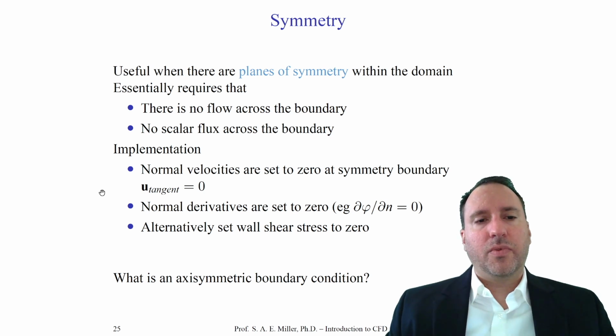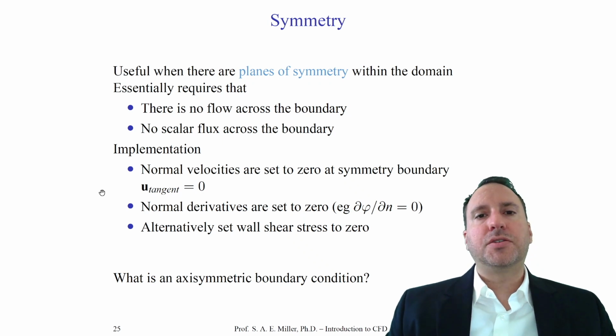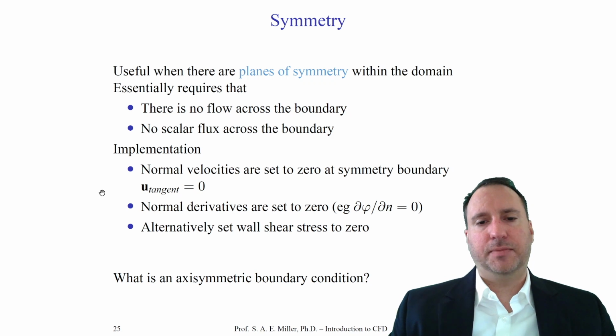So this would be a case where we set a plane, or line in 2 dimensions, within our computational domain with a boundary condition to mirror the solution about the symmetry plane. I talked about the symmetry condition earlier in the class, and it could reduce computational expense greatly.